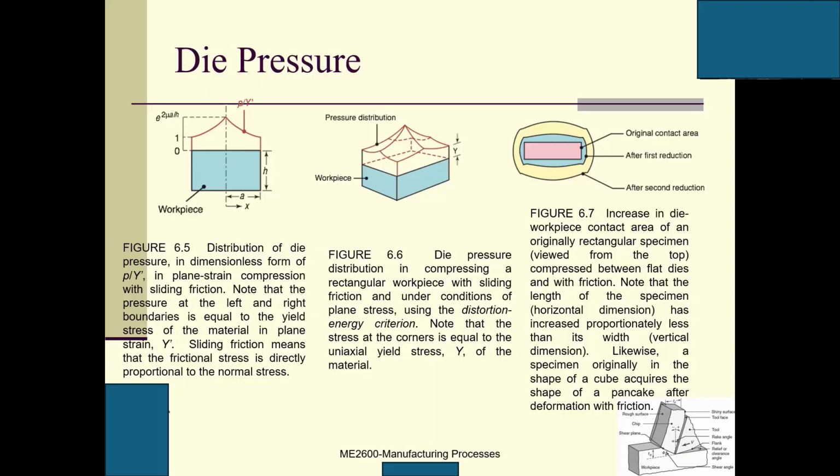Here, this is a thin plate, and this plane strain is a thick plate. Both of them are treated as 2D. So they are simplifications of 3D problems. Actually, they are 2D problems: plane strain and plane stress.